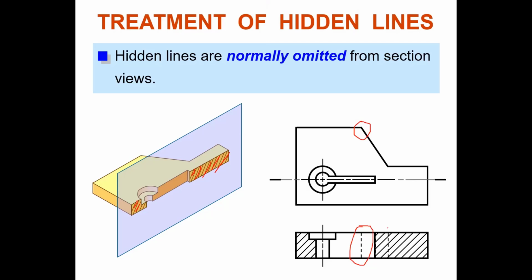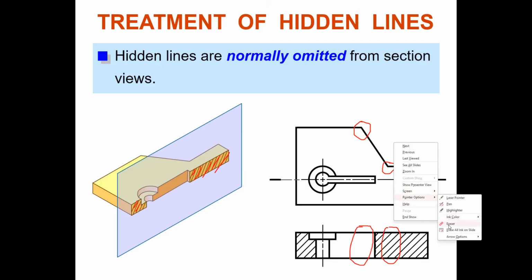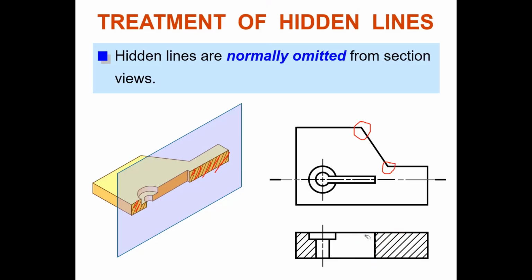Right? This hidden line is this corner. Clear? Do we put the hidden line or leave it? Nothing. No hidden line on the front view. Should it be put on? No hidden line. No. The answer is no. Clear? Do not. There is none. Understand? Many students make this mistake, because in the simpler version there is this idea. If you draw the hidden line, you do not make use of the section view. No hidden line. Alright.